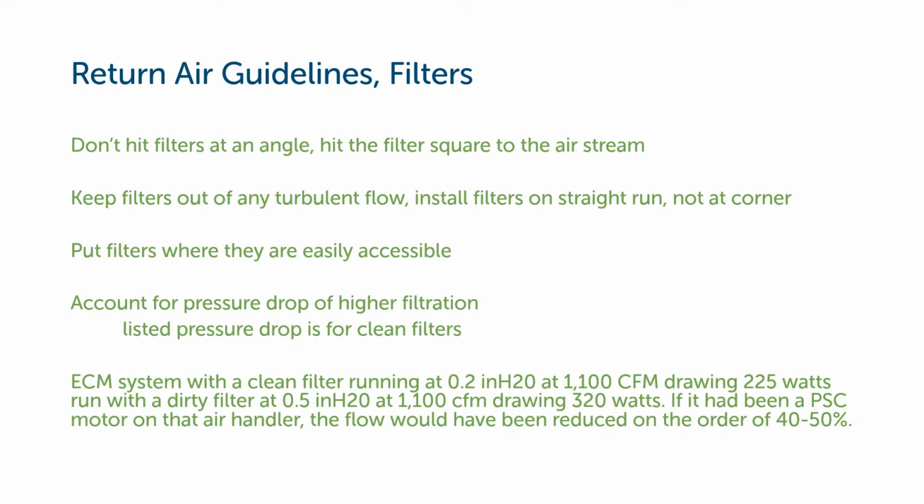So we want to keep the filters out of the turbulent flow. We don't want to install the filter near an elbow. Remember we saw where the turbulence is, right behind that elbow. We don't want to do that. We want to keep them in a straight run if at all possible. We want to make sure they're easily accessible.